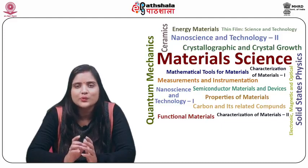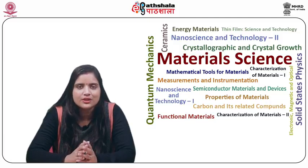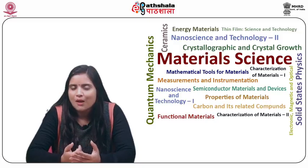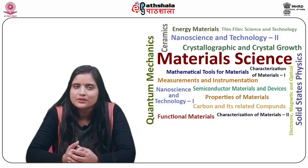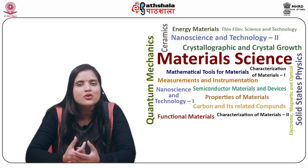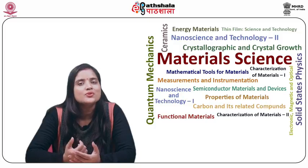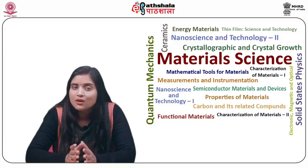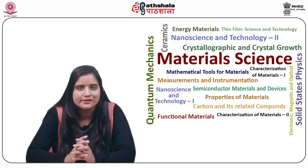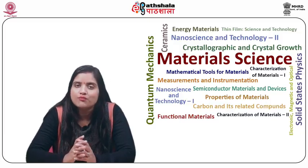Electroless low phosphorus nickel plating provides superior corrosion resistance towards alkaline conditions. Another application is medium phosphorus, which is bright and high speed. Medium phosphorus electroless nickel plated steel parts give performance similar to stainless steel. There is no buildup of electroless nickel on edges or ends, and it covers both inside and outside uniformly.